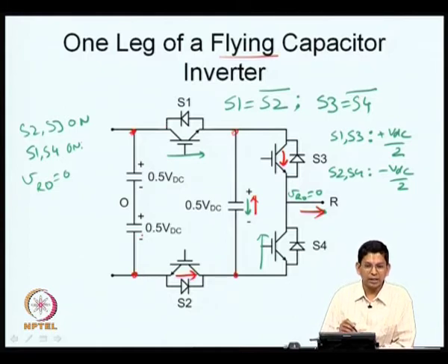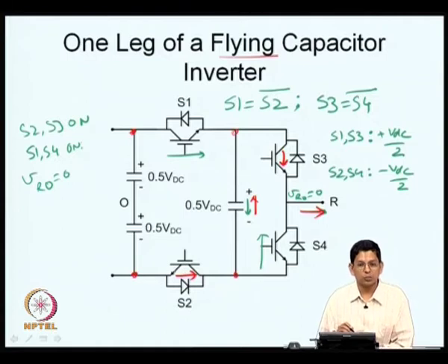So, you have a unique way of connecting the pole to the positive DC bus or the negative bus. But if you look at the intermediate potential, namely VRO equal to 0, you have multiple ways of doing this, and these multiple ways help you maintain the charge on the capacitor now. In flying capacitor, this is certainly a challenge for you to first have the capacitors charged to this voltage level and continue to maintain that the capacitors remain charged at these voltage levels now.